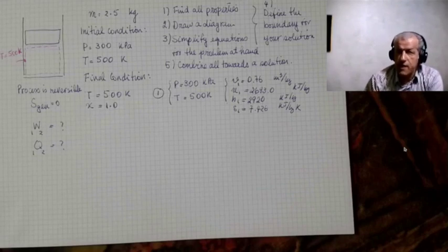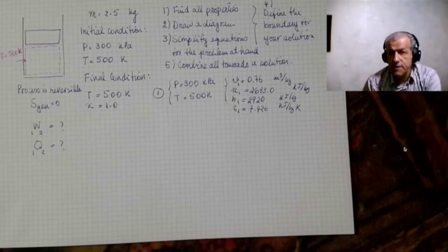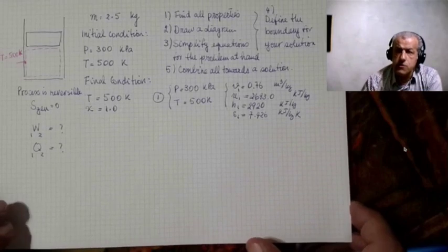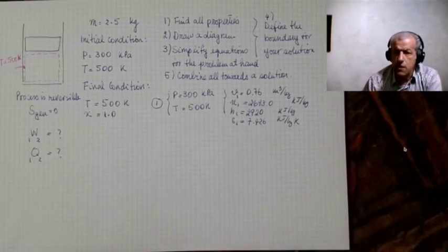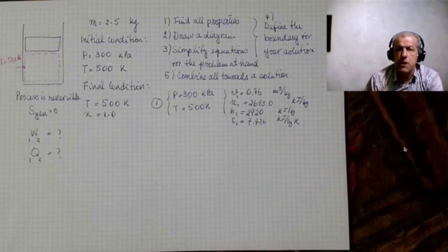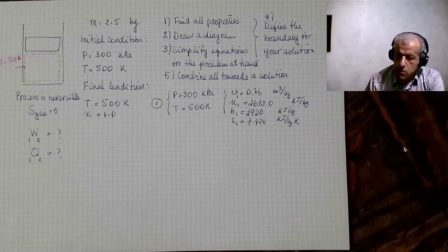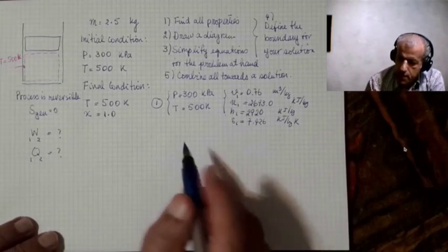But we can find properties of saturated material, like saturated water, like R134A, and else in tables, and entropies are also written there. So just like whatever property of water that we read from the table, entropy is also the same. So for condition 1, we have all the properties.